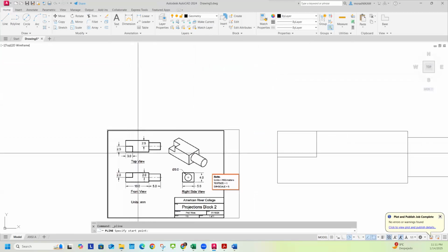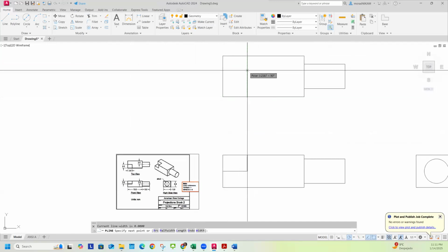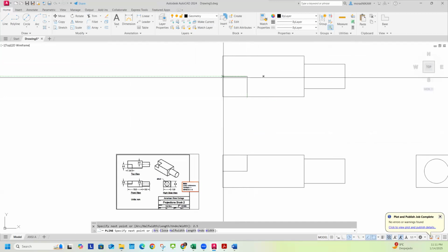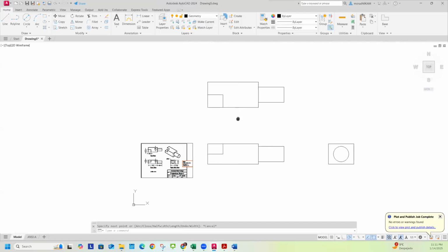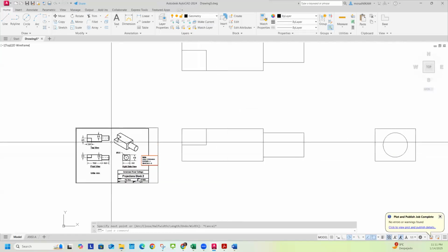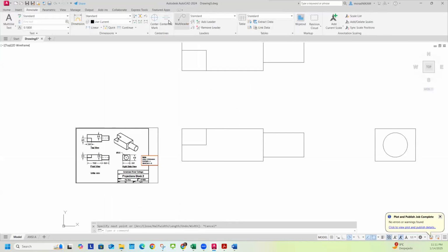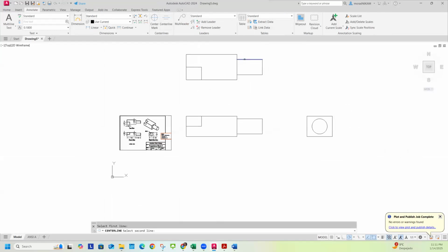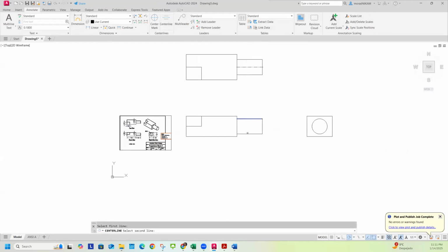And then this is going to be 3 by 2.5. So start tracking this way. I'm going to say 3, 2.5, and then end it right there. All right, and then I need to add a couple of center lines to this. So I'll go to annotate, and I'll choose center line. I'm just going to choose in between these two, and then one more time in between here.